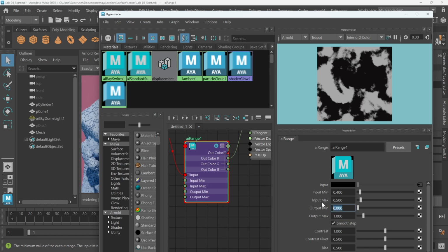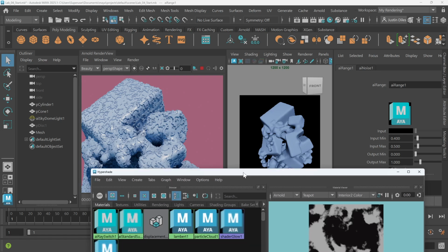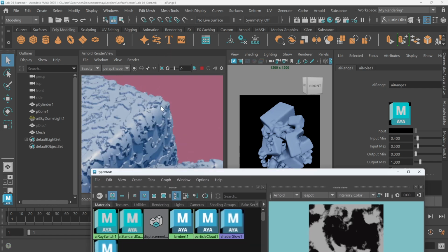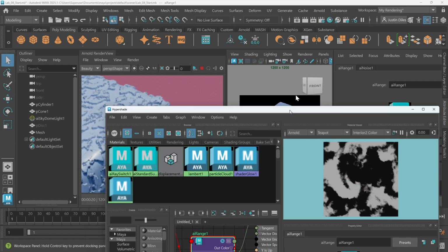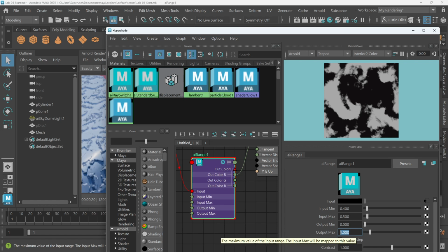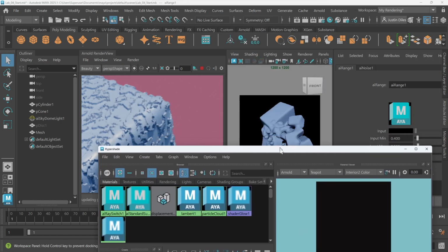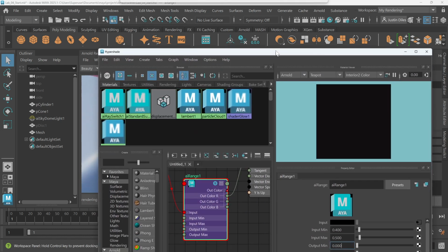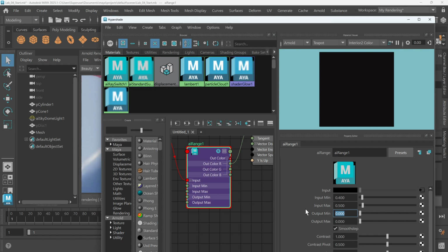Now, what this means is that with respect to our original mesh, our texture is only going up, and it's not insetting at all. And so what that means is, let me try this again. We can kind of see this here. We have our original surface, and then our texture is only going up from that surface. And if I wanted to maintain the original surface, I could set this to 0. And now it should go to smooth, and it does. And if I wanted the displacement to only move in, I could take this to say -0.5.